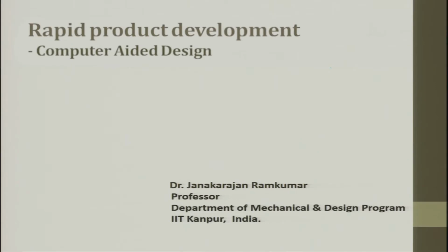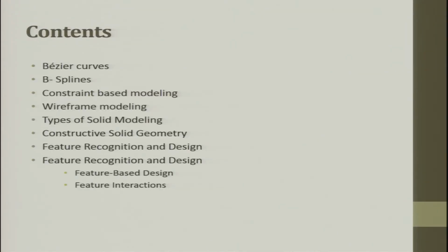Welcome back to the lecture on computer-aided design and manufacturing. We are more focused towards CAD in this lecture. Last lecture we saw more towards generic, simple 2D representation in CAD, and then we slightly extended how going from 2D to 3D has to happen. In that case, we started talking about translation and sweeping, two mechanisms or two algorithms which are inbuilt in 2D such that you can create 3D structures.